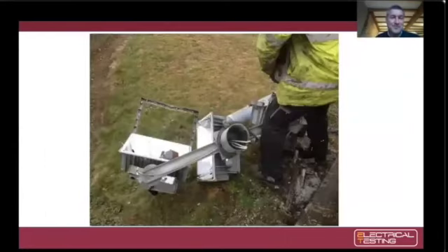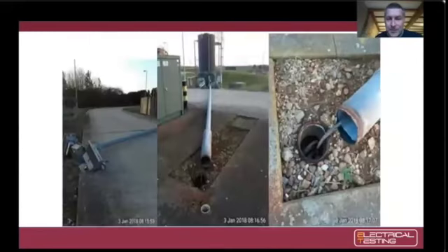This one is a floodlight configuration. It was put onto a 5 meter column, mild steel, tubular steel as well. You can see there is some ground level corrosion there, but it wasn't designed for the attachments, and the attachments again were a contributing factor on the column failing. So again, that necessitated testing the rest of the infrastructure, but not only testing it, it was then obviously getting the lantern information and the floodlight information and putting it through the calculation process.